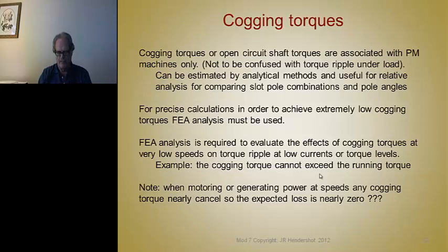If you have a 4-pole motor and 12 slots, and if your pole arc is 2/3 of a full pitch, being 60 mechanical degrees, that gives you the maximum cogging torque amplitude. And the reason is because the sides of every one of those magnets will line up with slots. So you have 4 magnets, you got 2 sides, that's 8 sides. And so all 8 sides of those 4 magnets will line up with 8 slot openings in the stator.